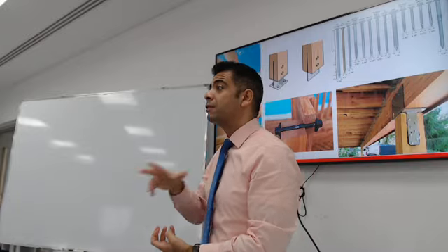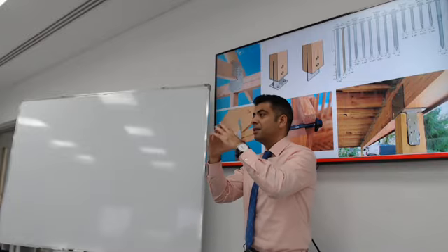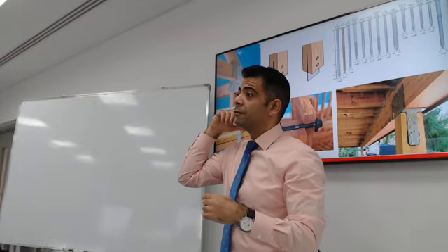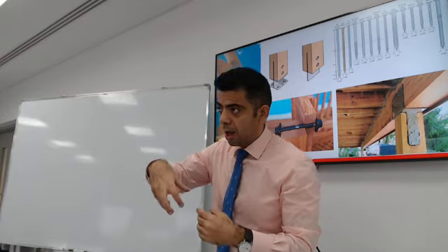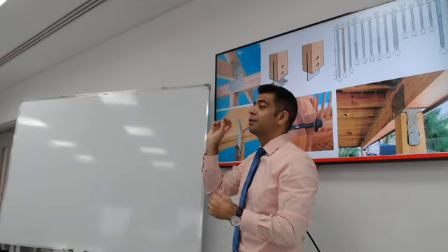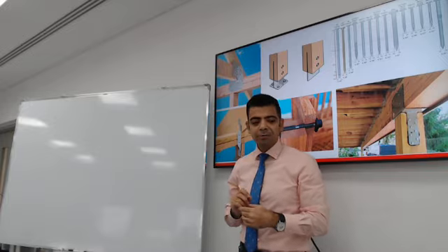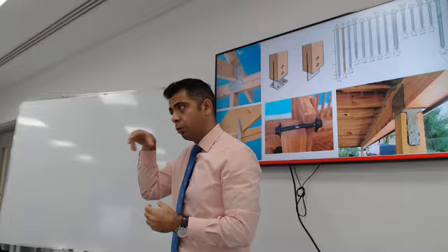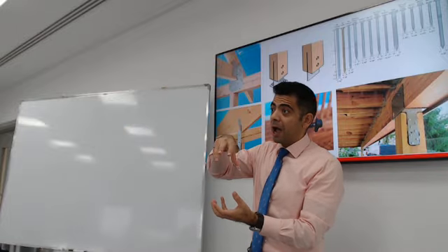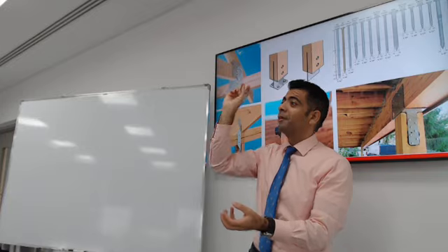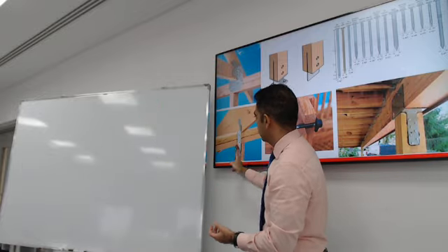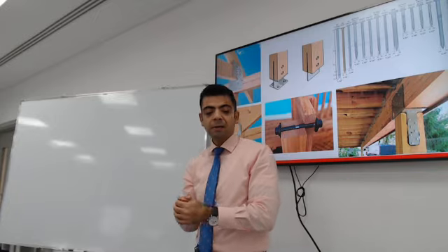When you do the wind tunnel analysis and you test the effect of a storm on a roof, the very high wind velocities will cause upward force on the roofs. There are a lot of videos on YouTube, you can look them up, in a storm where a tornado or a twister actually sucks up the roof of a house clean off the building. So these ties will work as the connection between the roof and the walls.